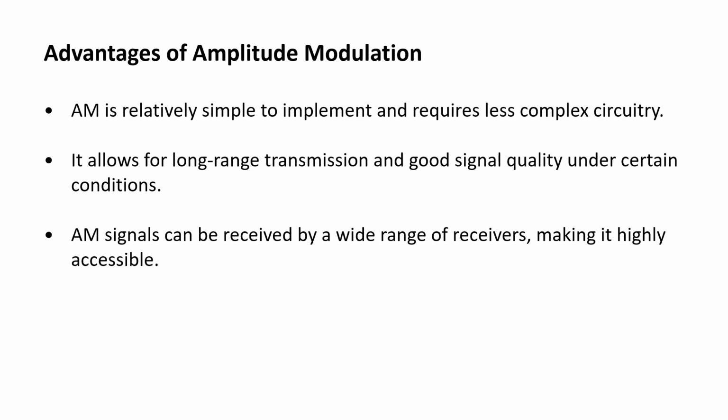Bandwidth efficiency. Amplitude modulation signals typically require less bandwidth compared to frequency modulation signals, making them useful where bandwidth is limited. Multiplexing possibilities. Amplitude-based signals can be used in multiplexing techniques such as frequency division multiplexing (FDM) to transmit multiple signals simultaneously.